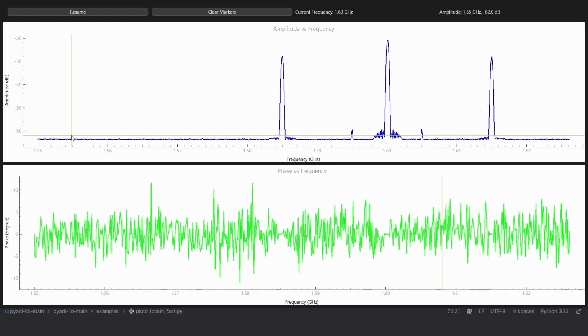But with these high frequency locking amplifiers, because your frequency is high, your circuit sizes and your cable sizes become comparable to the wavelength lambda. It means that when you are changing the frequency, you are essentially changing the wavelength, which will have an effect on the phase. We will see this in other examples that I will talk about in our next videos.